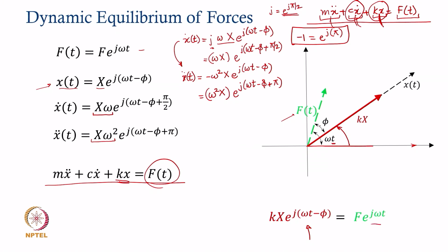That omega t minus phi is the phase between the force and the response. So, this will align like this, which is of course aligned with the response. So, Kx, the amplitude of the restoring force with proper orientation or angle made, is going to get aligned like this. This is going to be the restoring force Kx.